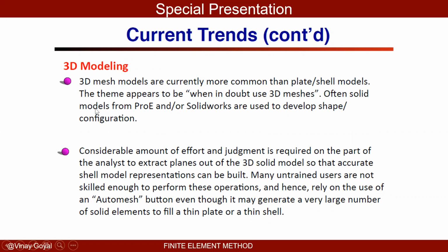Okay, the current trends are that 3D mesh models are currently more common than plate shell models. The theme appears to be, when in doubt, use 3D models. Often the solid modeling from Pro-E and SolidWorks is used to develop the shape configuration, which could be good, which could be bad, because you need to prescribe the proper boundary conditions. Most of the time, people have trouble with the boundary conditions. So let's skip this chart.